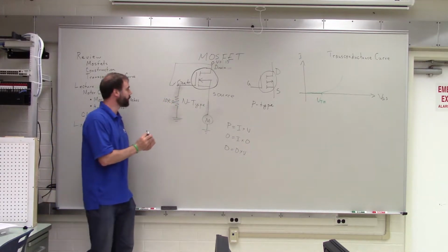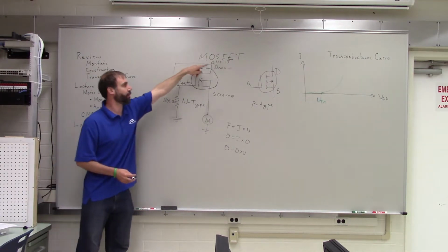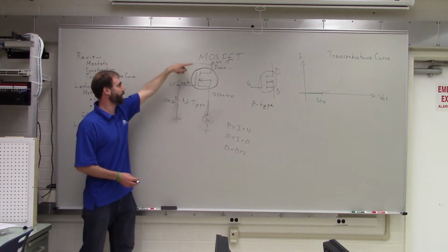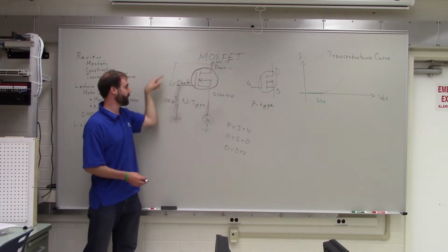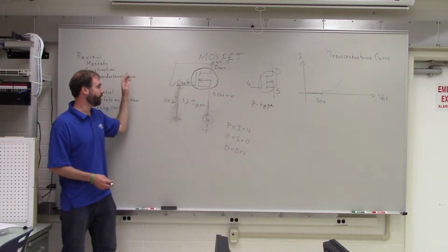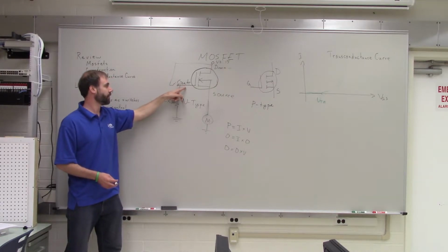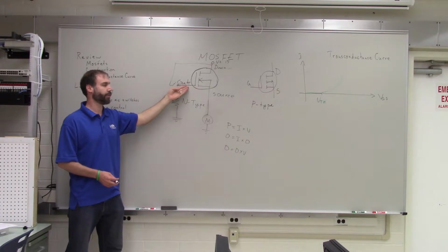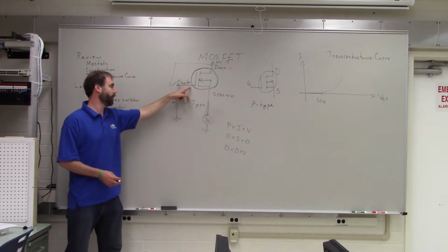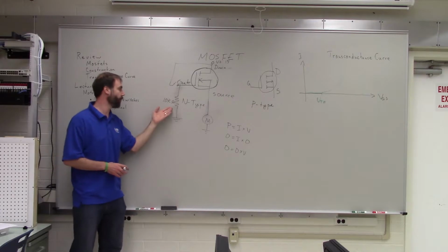So when the switch is closed, this voltage at the gate is still about 15 volts, right? Because the gate is connected directly to a 15 volt supply with a wire, so the gate gets 15 volts. Now, when the switch is open, any sort of lingering electrons, lingering charge that was on the gate drains down through the resistor to ground, and this gate voltage gets pulled down to 0 volts. So that's why we call this a pull-down resistor.